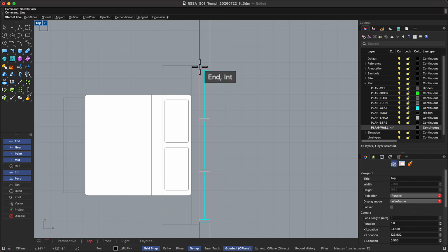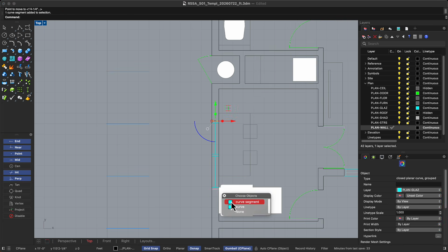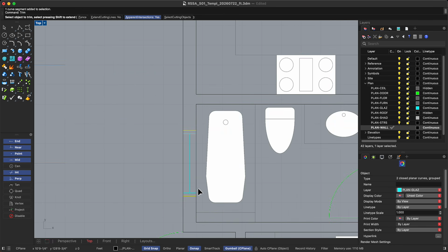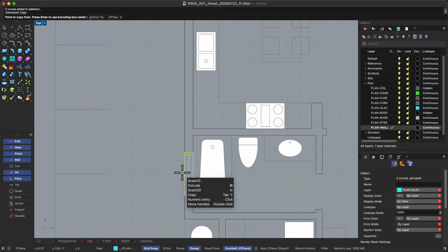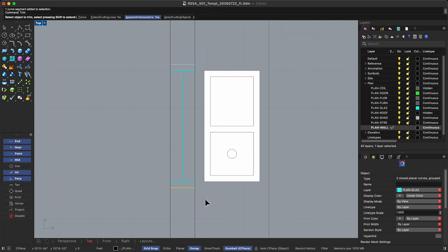When placing windows, align each one with a clear reference point in its room. For example, center the bedroom window on the bed, the office window within the width of the room, the bathroom window on the tub, and the kitchen window on the sink. Openings are part of the enclosure, but their line work should read lighter than the solid wall being cut.